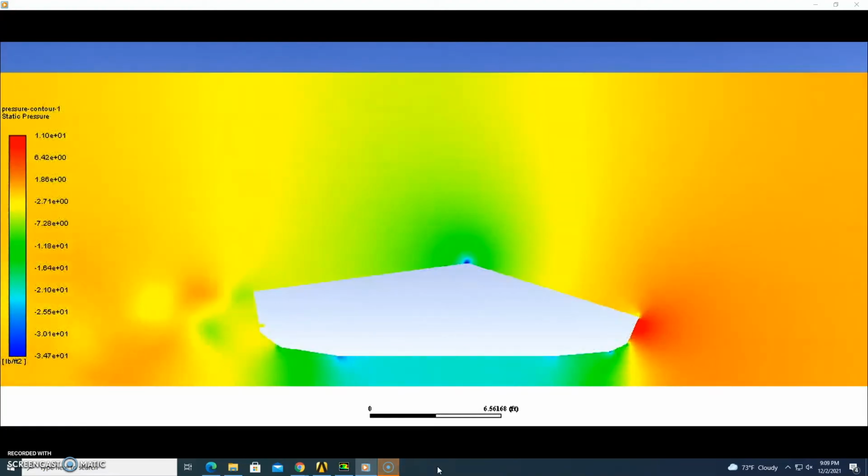Here you can see the pressure contour animation. From the animation, you can see that the pressure is pretty uniform throughout the top end of the 2D profile, which seems to be a goal in designing the Cybertruck. However, a peak point can be viewed at the top end of the vehicle and plays a critical role in why the vehicle is pretty aerodynamic. At the end of the vehicle, you can see the pressure changing quickly due to the separation of flow and the formation of vortex shedding.